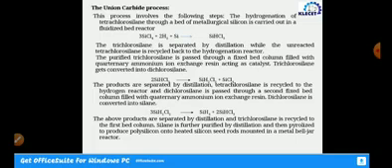After purification by distillation, the silane is subjected to pyrolysis to produce polysilicon onto heated silicon seed rods in a metal bell jar reactor. So I form the polysilicon here. This is the synthesis of polysilicon by the Union Carbide process.